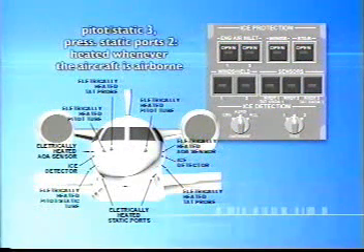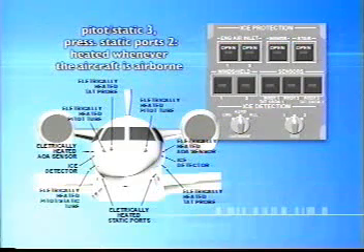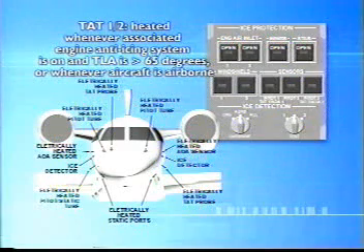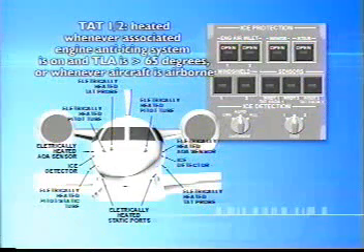Pitot Static 3 and Pressurization System Static Port 2 are heated whenever the aircraft is airborne. TAT-1 and 2 are heated when the associated engine anti-icing system is on and thrust lever angle is greater than 65 degrees, or whenever the aircraft is in flight.